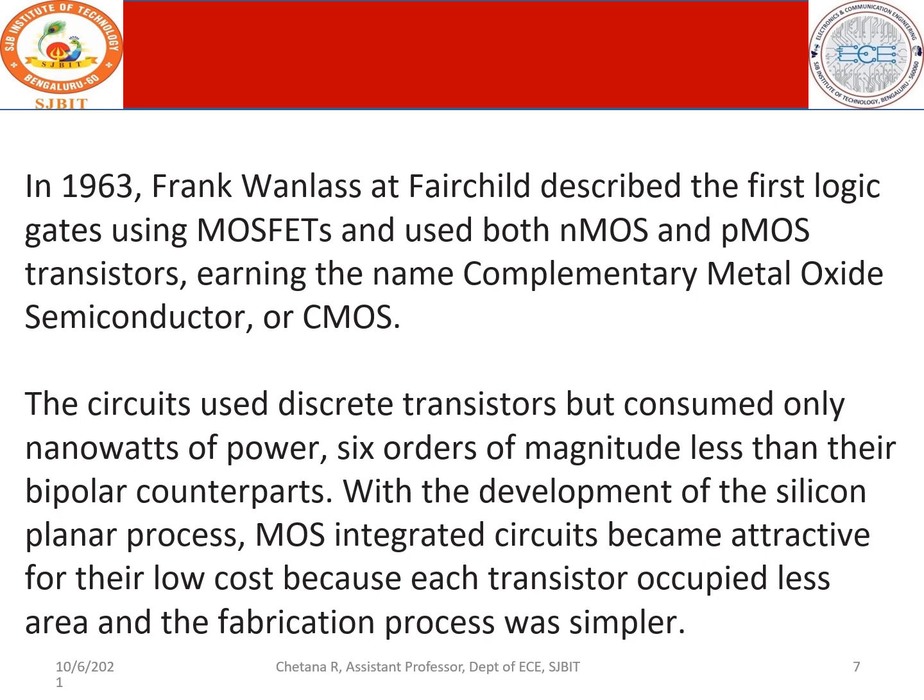Why complementary? When you look at NMOS and PMOS, NMOS is a device constructed on a P substrate, and electrons are the majority charge carriers, whereas PMOS is constructed on an N substrate, and as a result holes are the majority charge carriers. So both are complementary in action. Here electrons work, here holes work, and if this works in negative voltage, this works in positive voltage. So in each and every aspect, NMOS and PMOS are complementary. They have reverse working principles, and therefore the combination of these two is called complementary metal oxide semiconductor. So these circuits used transistors but consumed only nanowatts of power.